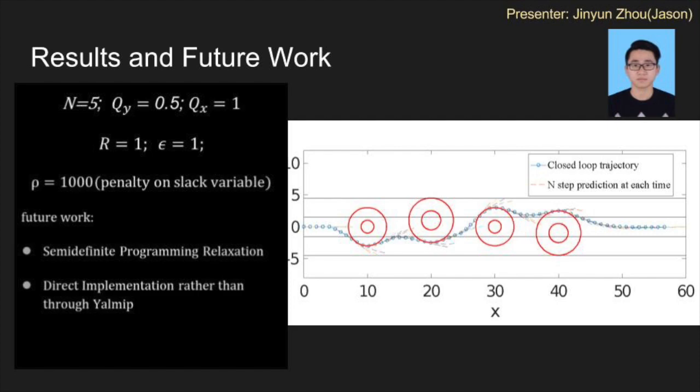The rho and epsilon are to make the sequential convex program iteration converge properly. The derivative of the steering angle is limited to avoid oscillation, which occasionally happens when the truck encounters an obstacle whose center is just on the original track.